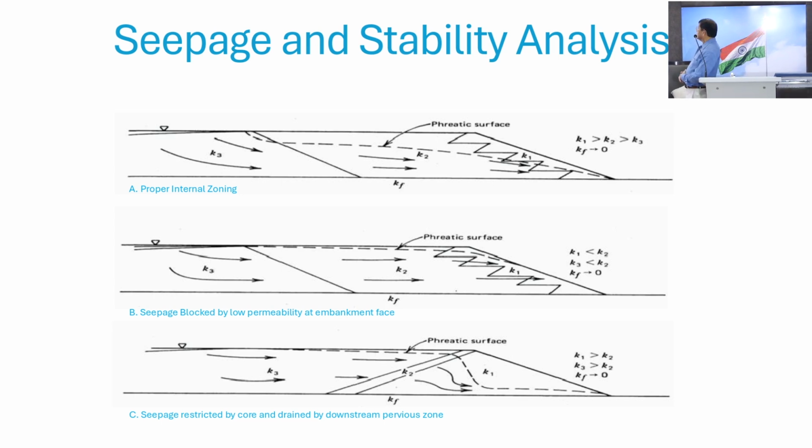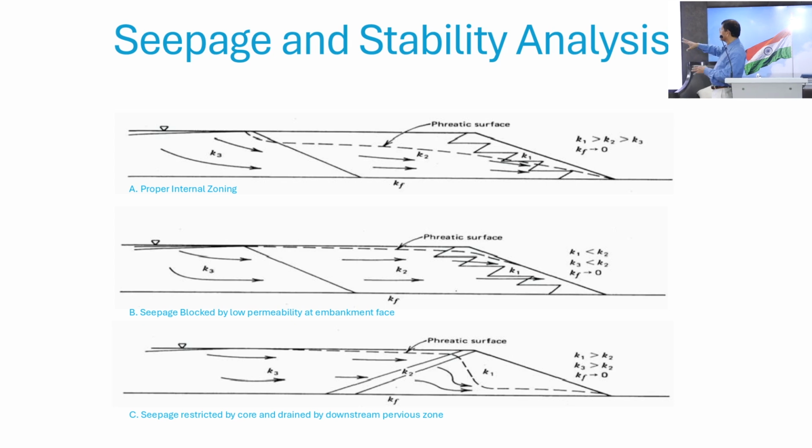Remember, mostly in the downstream and central line, we are showing you the use of the filter. If you put the filter, then that also keeps the pore pressure down. That's another important thing we do in the downstream and central line.